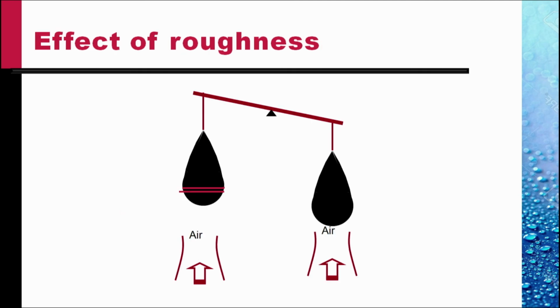Now, another curious phenomenon in drag is if we analyze the drag on the bomb-shaped body, the streamlined bodies, and investigate the effect of roughness. When we investigate the effect of roughness on streamlined bodies, we see a phenomenon which is directly reversed of what we saw on bluff bodies.